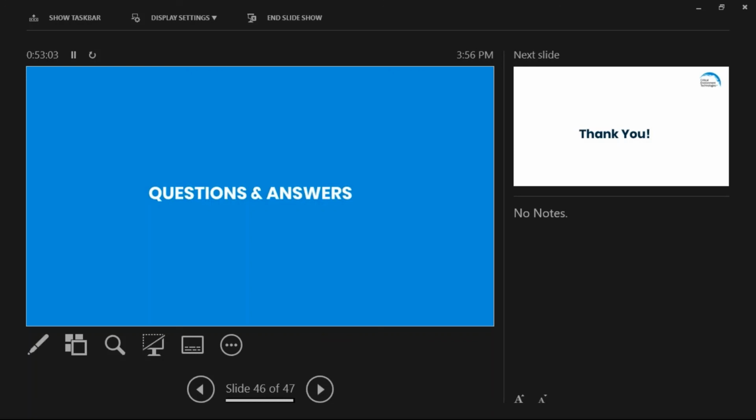If your sensors are being installed to protect people, and typically NO2 and carbon monoxide sensors are installed to protect people, you want those sensors in the breathing zone where the average person is breathing.